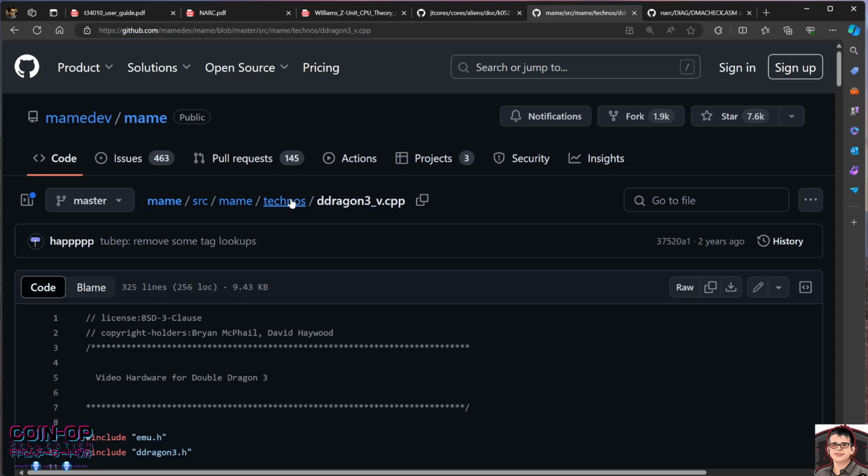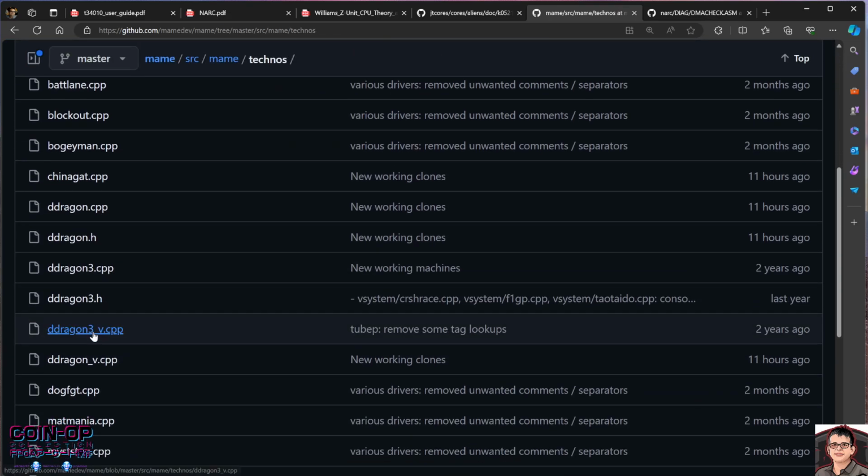It doesn't even appear anywhere, not even as a comment in the code. So I actually had to break out the board. I had to hook up my logic analyzer to it, and hook up leads to the 68K IPL pins, see what the rate is, and then create a clock enable for that rate and hook it up to the 68K in my FPGA core in order to make things work. Okay, so you might find yourself doing that.